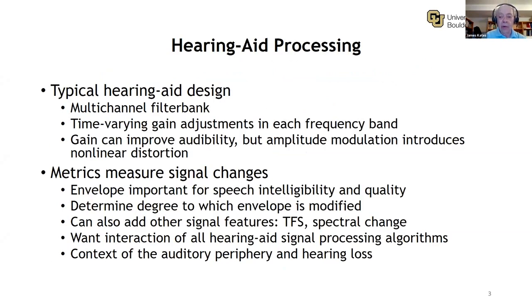Carolina gave a short overview on some hearing aid processing. Since I'm an engineer, I'm going to take more of an engineering approach to this, which is what is going on inside the typical hearing aid. The general design is a multi-channel filter bank with time-varying gain adjustments within each frequency band. Now, if we increase the gain in a hearing aid, that will improve the audibility of the speech. So that ought to improve speech